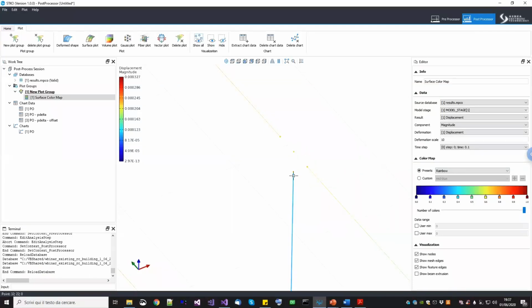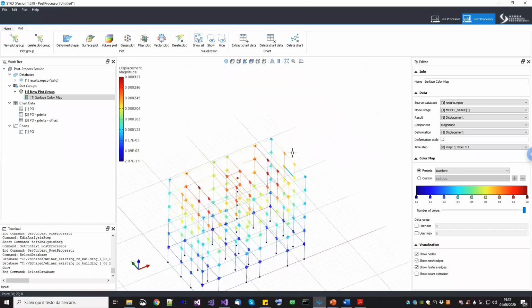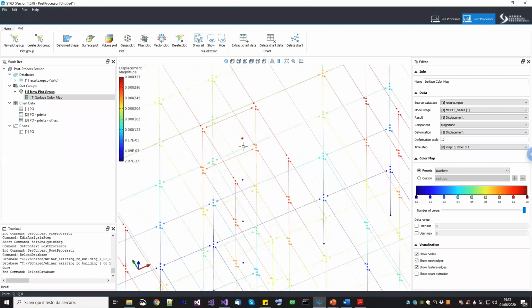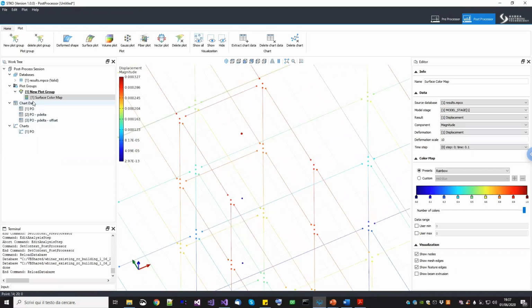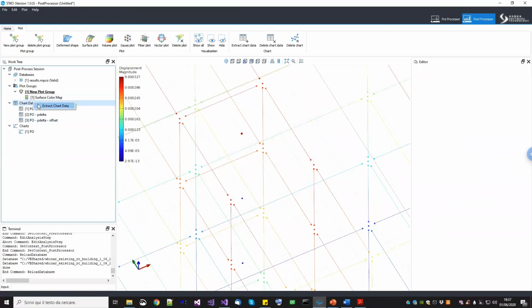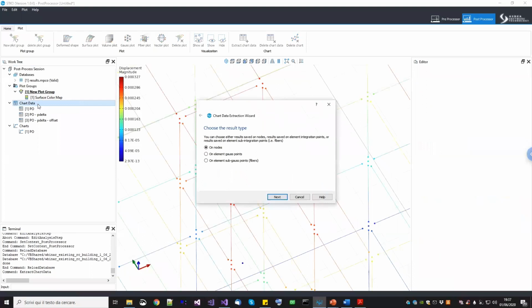So two nodes, one connected to the column, one connected to the beams, and the two of them are connected together using the scissor model. Okay, and then of course in these blank spaces here you have a rigid link constraint. This is a rigid body constraint, so no element has been drawn here. Okay, so I keep on selecting this one, and I try to export the pushover data. It should be almost the entire curve. But if it is not, I will open the results of the material that is already there, because probably I made some mistake in the material properties, but it is fine.